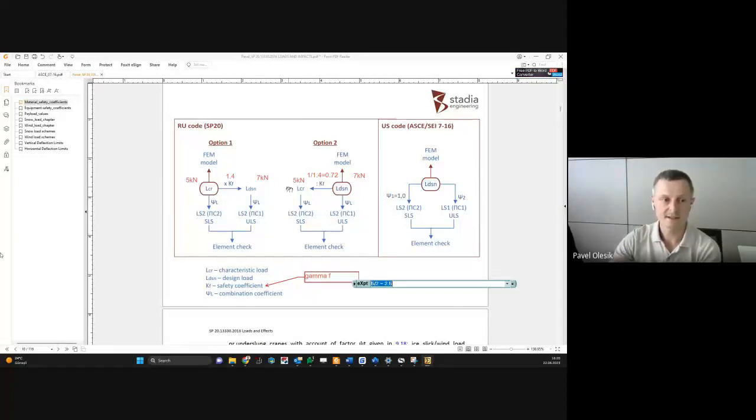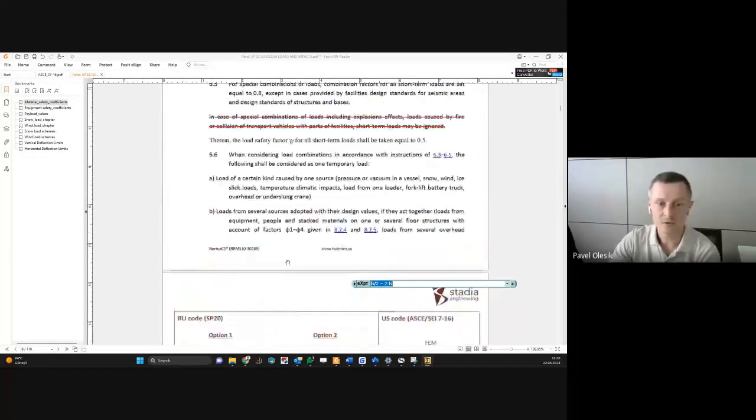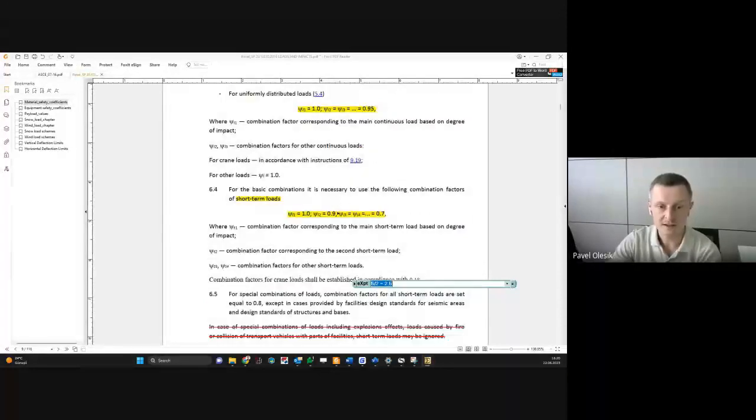In this case, I would suggest you work with combinations. And in these combinations, for the snow factor, I would recommend putting not 0.9 but 0.45. So it will be a 0.45 factor, like this. Different ways, but you can use any one.